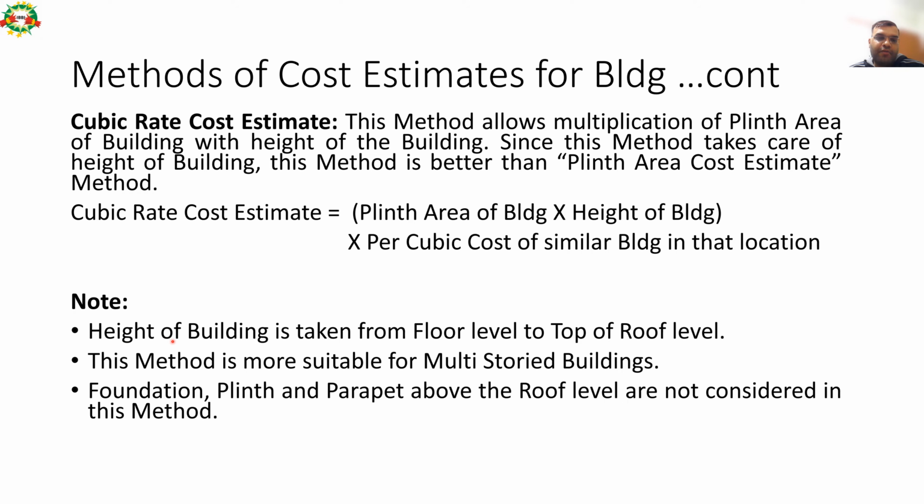Here the height of the building is taken from floor level to the top of the roof level. So please note these things. This method is more suitable for multi-storied buildings. Foundation, plinth, and parapet above the roof level are not considered in this method.